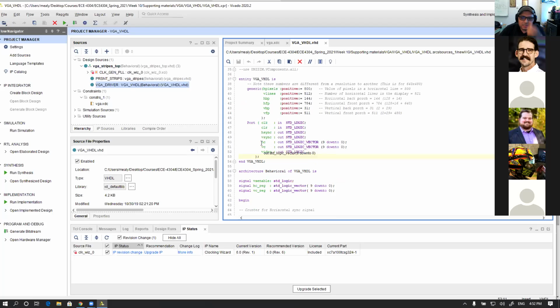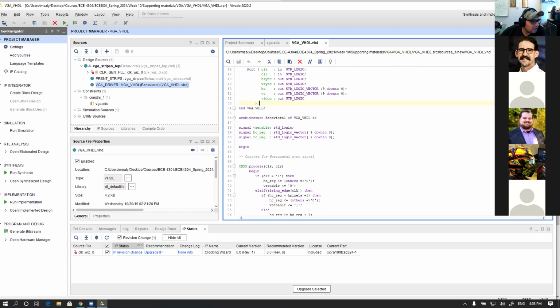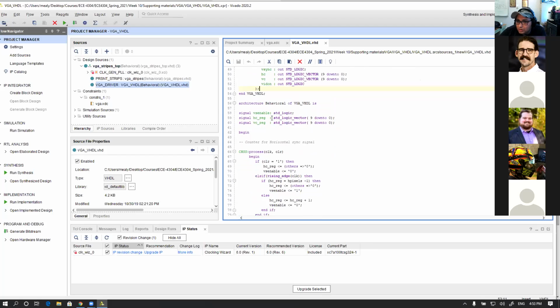Now I decided to make the counter count 10-bit because I'm reaching 800. So if you go up to 800, making it 10-bit is better for you because it's going to be 1024, right? Now we also start defining some temporary registers because I don't want to hook it directly. I like to make everything in a temp, and then I will push it to the IO. This is my strategy since we started, even with VHDL.